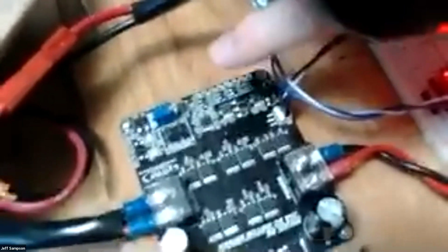If I were to disconnect the power right now, let me pull off the PWM, the white one. If I pull off the white one, I have to be careful I don't smash my pot now because there's nothing limited. But just pushing the buttons will run it back and forth. So there's a place on here for the switches. There are some pads. You could run wires out and put 2 push buttons somewhere on your vehicle. And for the pot, you can set a jumper that uses the external pot. So there's some wires over here, and you could put a 1-turn pot somewhere on a panel.